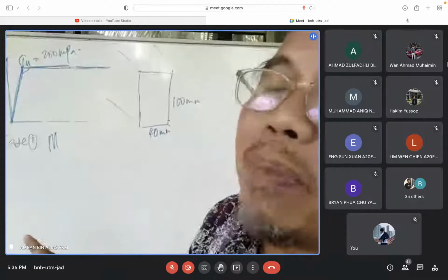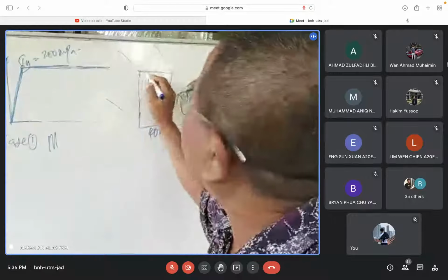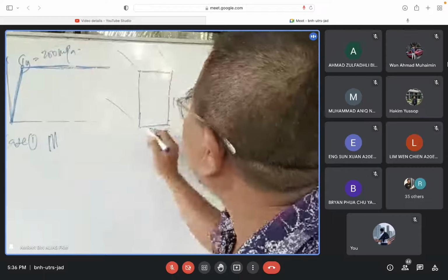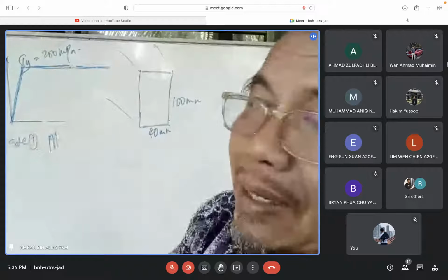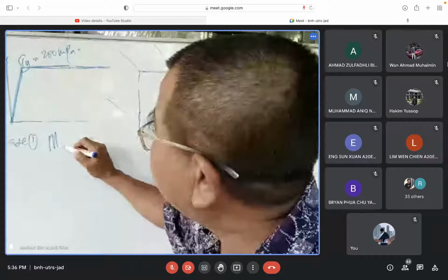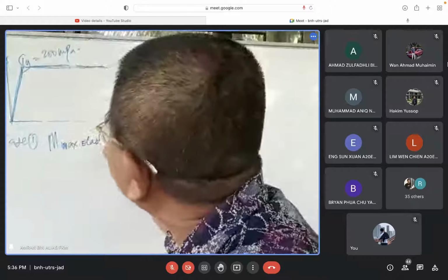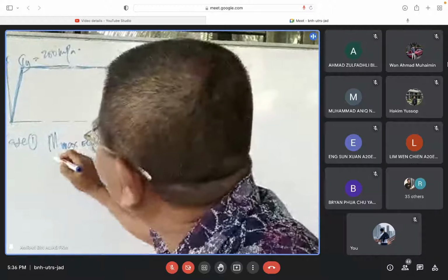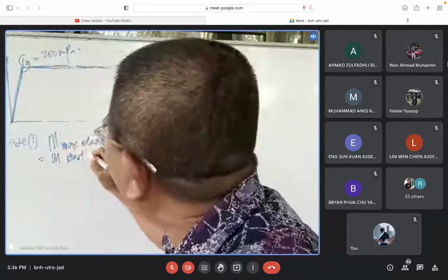To start plastic means what? The surface here, the top and bottom, the stress must equal the yield stress. So we call it moment maximum elastic. Some people call it maximum elastic. This is equal to moment start of plastic.